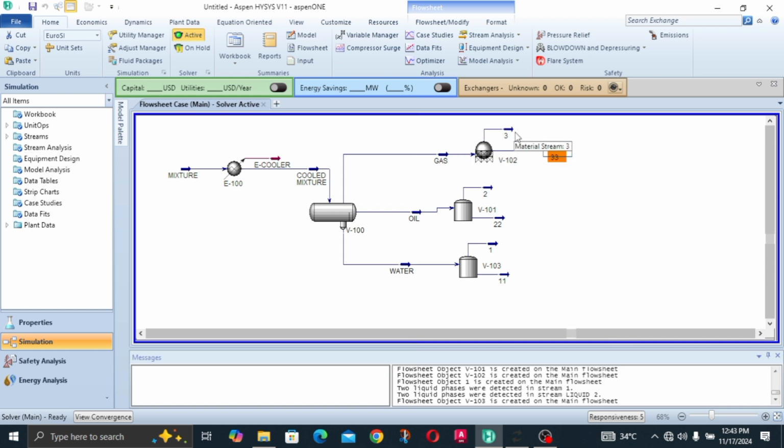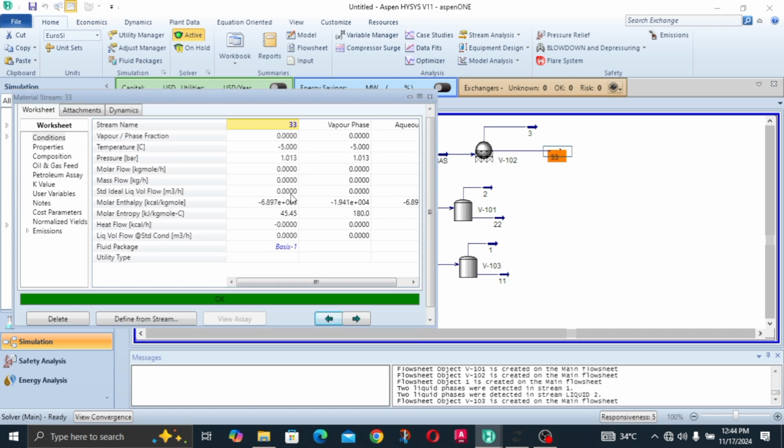Spherical tank for the gas. And remember, it's a gas going in here, so we expect that there should be nothing. This bottom stream is the liquid. It's not supposed to be there initially, but Aspen Hysys expects you to label the vapor and liquid outlets always for the equipment to be successfully operated. So you just have to name it, but there is basically nothing inside. As you can see, the flow rate is 0.